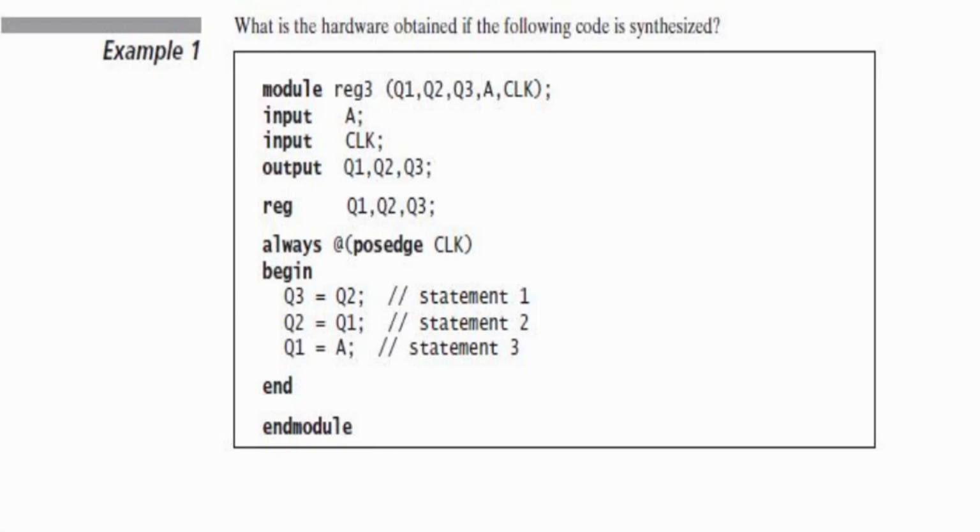If you notice, you can divide those ones and zeros into sides and edges of a square. There are four parts. One when the clock is 1, it's stable, and another when the clock is 0, it is also stable. Then there are two edges, one rising edge and one falling edge, or a positive edge and a negative edge. In a positive edge, the value goes from 0 to 1, so it's positive.